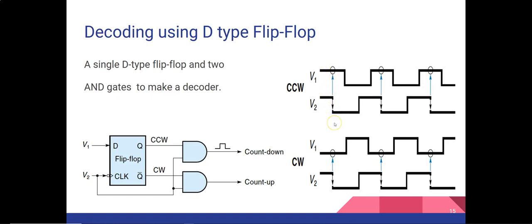Then your output is also going to be high. It is going to follow this until the next clock pulse arrives. So the output, which is Q here, is going to be high till here, and it will check again and see what the input state is, and here again the input is high. Then it will keep the output state high until the next pulse, and that's how it works.